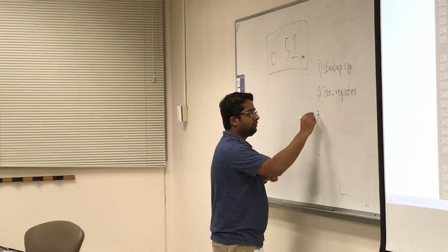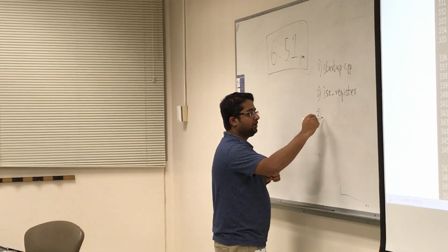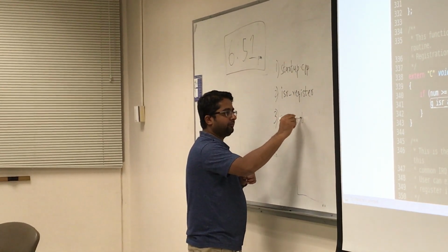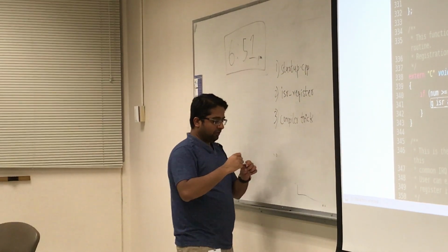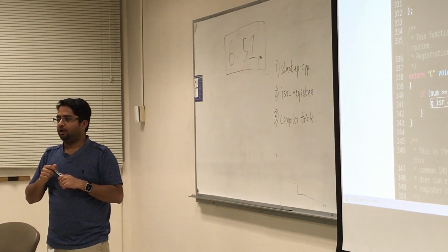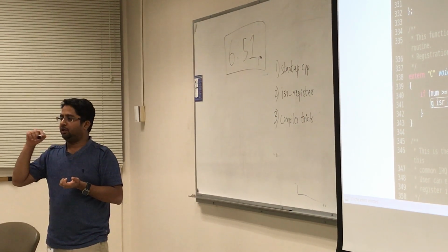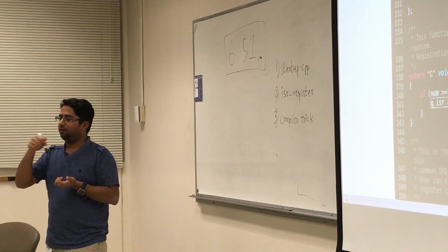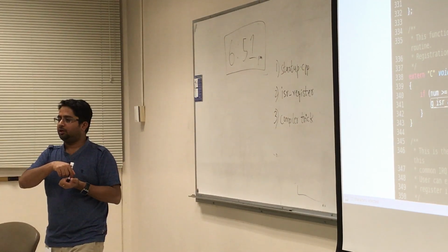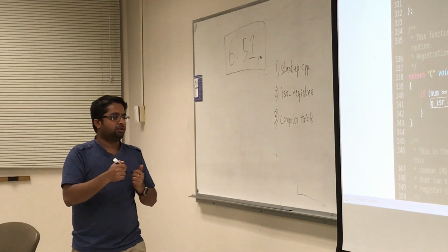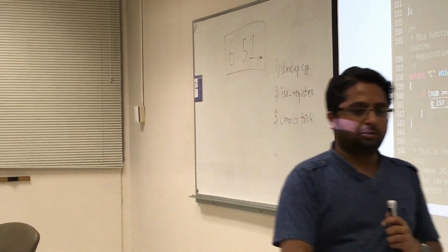And the third way of doing an interrupt is what is called the compiler trick, where you actually tell the compiler that for one of the interrupt routines, I'm going to be defining how exactly it needs to work, so that it will override whatever the system has defined earlier. So to actually understand this more, can you open up startup.cpp again?